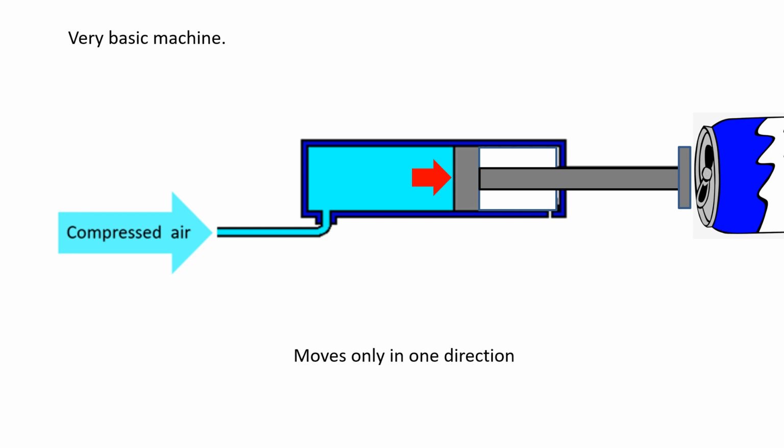When designing, repairing or maintaining pneumatic circuits, we need to understand how the mechanism works and its purpose. Questions to ask. How does the mechanism work? How will I control the flow of compressed air? Is the mechanism completely operated by compressed air, or are there other energy sources involved, like potential energy, springs, gravitational energy, weight, kinetic energy, movement?